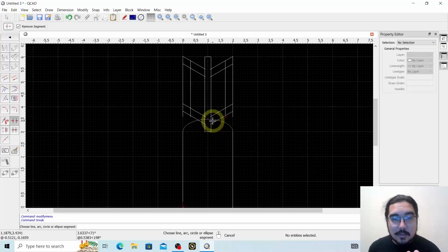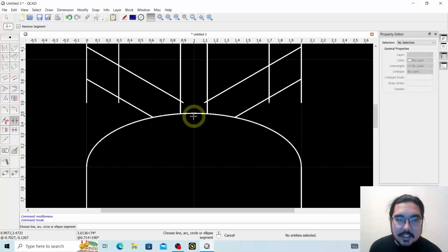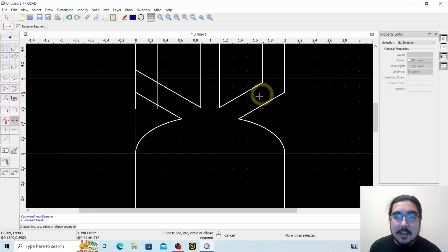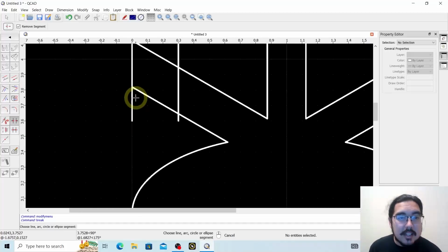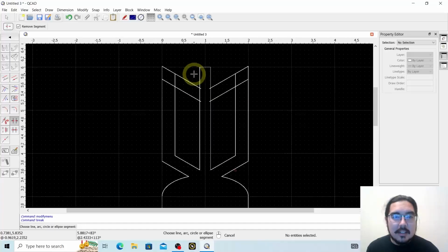Let's go ahead and zoom in and start to work with some of the more detailed pieces. This shaft that's sticking out the end isn't necessary here or here. Again, just deleting lines, deleting shapes, and deleting there, because everywhere I delete, it's going to be connected to some material. This is a slightly tedious process, but we're deleting where we want material to exist within this cut. Within the shape, any line that remains is going to be cut out, and obviously you don't want to do that. 1 and 2. There we go, and let's hop up to the top here.